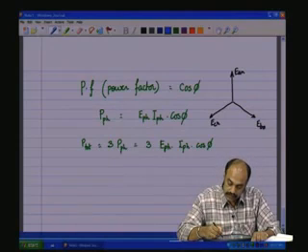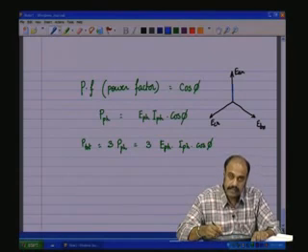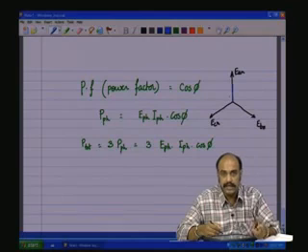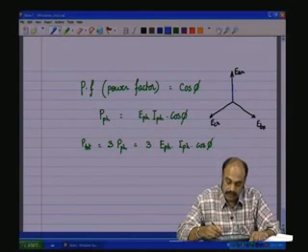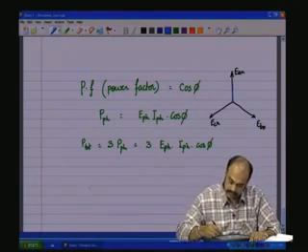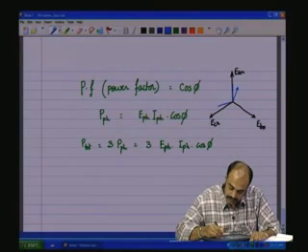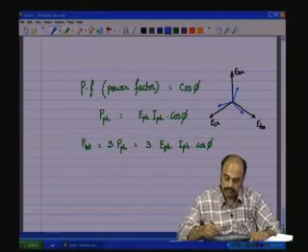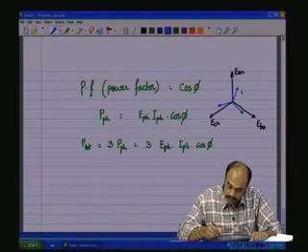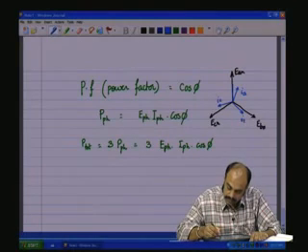In a resistive network, the currents are going to be in phase, but in the case of, let us say, an inductive RL circuit in the three load arms, you will have a current which is lagging each of the phases. So, this would be IA, IC, this is IB.